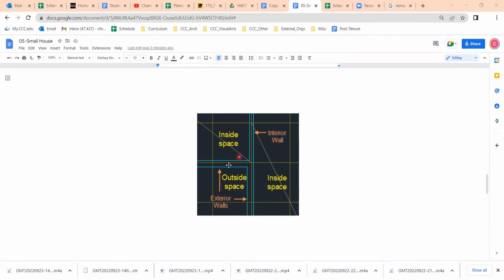So 2.5 and 2.5. And down here where we have these exterior walls, we have the same relationship on the interior side. So let's say this is a living room, for example. The walls are 2.5 inches in from the grid line on the interior side, but on the exterior side, they're 5.5. And again, that is so we can get whatever finishes we're going to put on the exterior, plus the possibility of having thicker walls for insulation. So total width of 8, total width of 5: 2.5, 2.5, 2.5, and then 5.5.